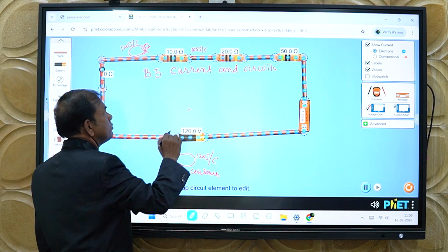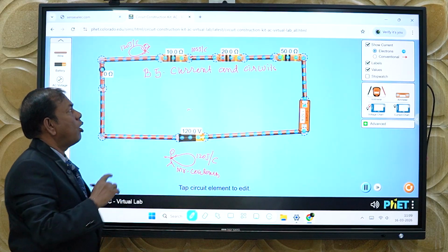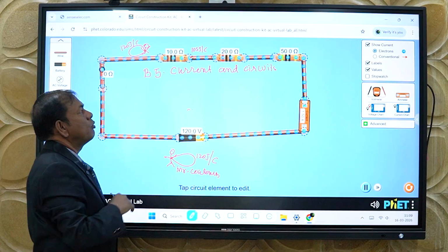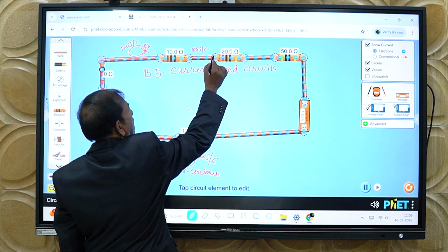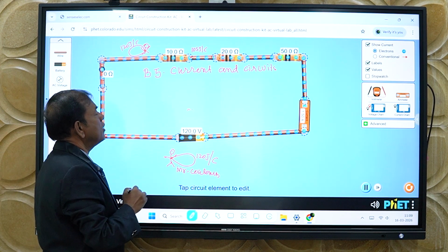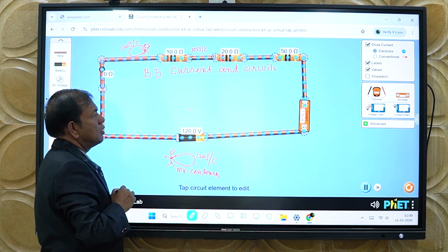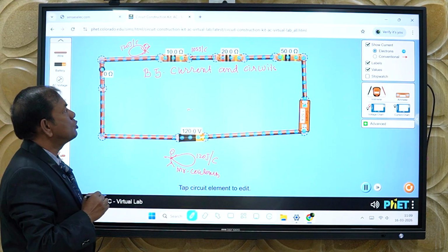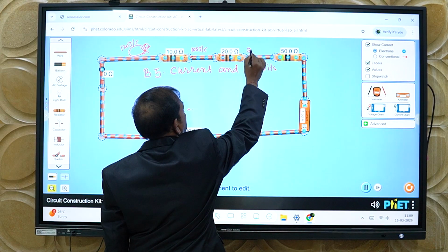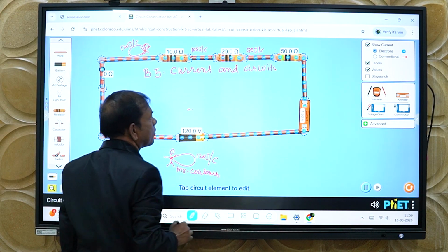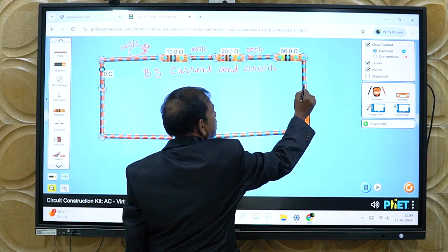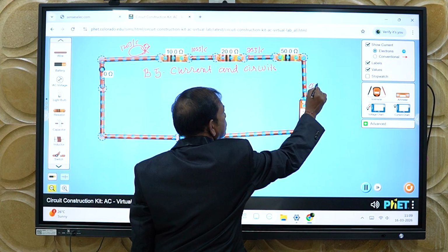Similarly, this resistance will also oppose the flow of current, so Mr. Coulomb has to supply some energy to this resistance so that he can pass through it. So here say energy is 105 joules per coulomb, and this resistor required something like 30 joules of energy. So the energy left out here would be 75 joules per coulomb, and the entire 75 joules of energy will be supplied to this 50 ohm. So energy left out is 0 joules per coulomb.